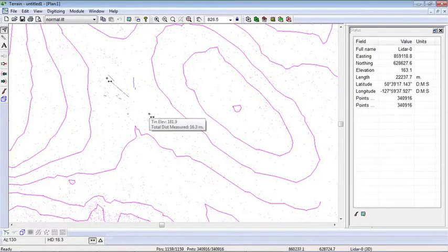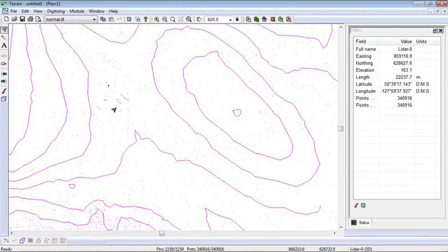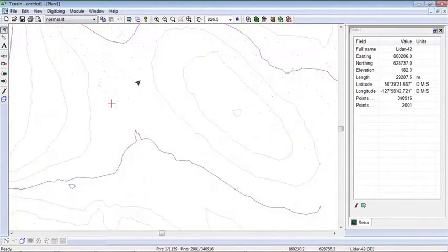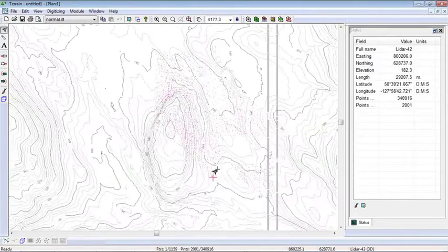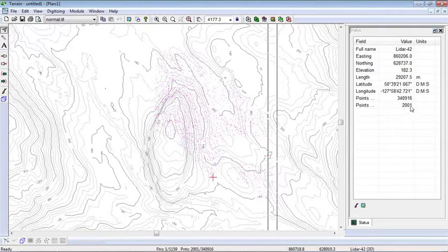You've got to be a little bit careful when you do that, because the points come in clumps. Like if I select this point here by clicking on it, you can see that there's a chunk of points highlighted. In fact, 2,001 of them. So when we read in the LAS LiDAR data, it doesn't put the points in single features. It clumps them in groups of 2,001. I'm not sure how that number got selected. So it's not that easy to select by boundary and get a point count. You kind of have to break them up. Anyway, the points in the canopy area, in the gaps, are around 20 meters apart. Looks a little closer over here.